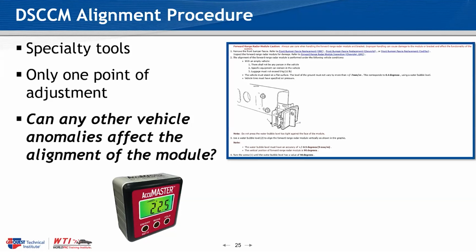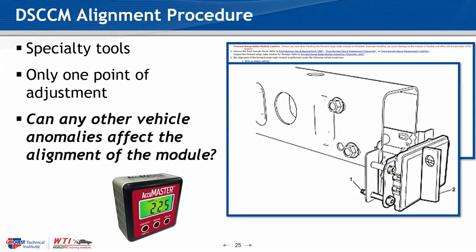After that was all repaired, the front frame section was replaced and a new mounting bracket was installed. It came with the hardware. If you look close, there's a non-adjustable bolt at the top left, a non-adjustable bolt at the top right, which had a couple of nuts stacked, you guys saw the picture, and the bottom left is an adjustable hex head, an Allen head.